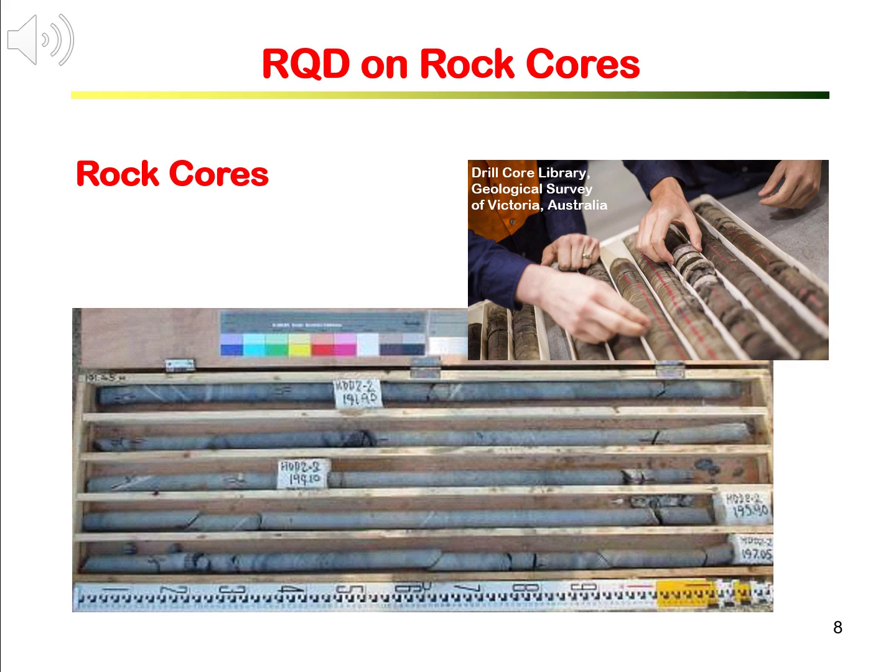Another key logging activity is measuring RQD from those rock cores. The photo shows cores typically laid in core boxes from drilling. The core can be different diameters, and the most common size for site investigation drilling is the N size, which is around 50 mm.